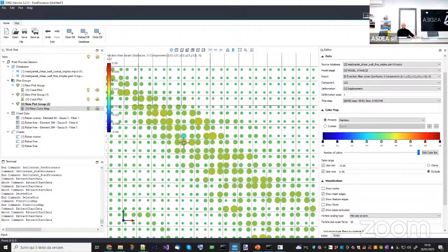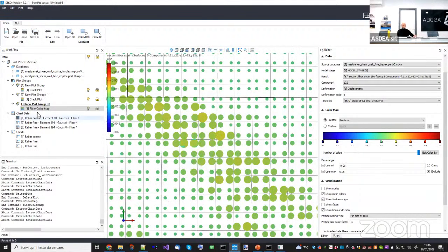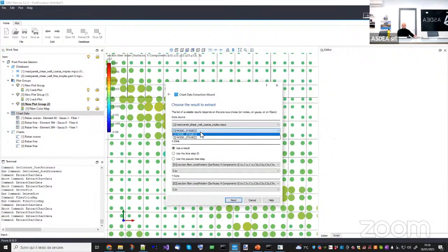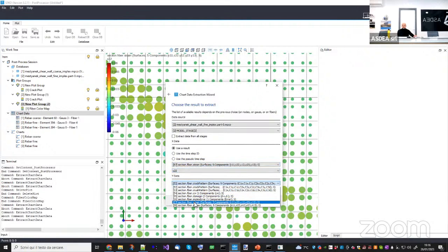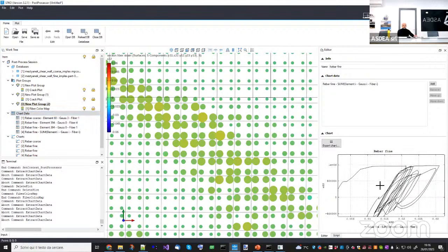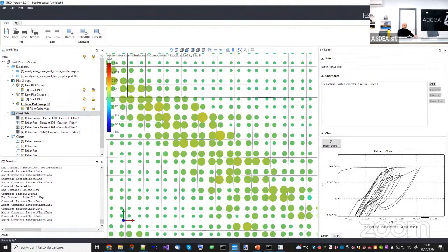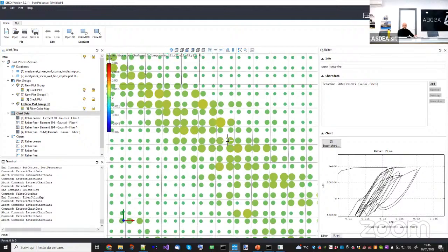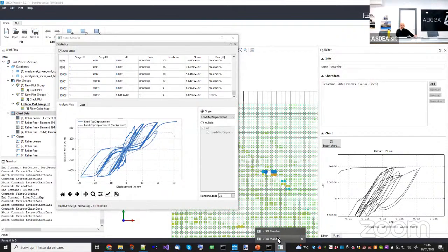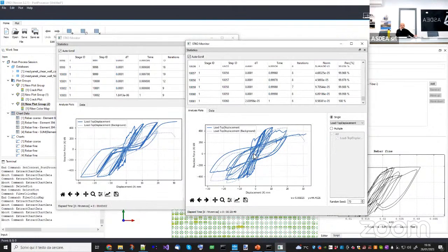So if I extract, for example, this one, probably before I picked one rebar that was not too much into plastic regime, but this one you will see much more deformation. So fiber strain, stress, vertical, rebar fine. Well, I picked two of them now. But as you can see now, the deformation is much larger. It's reaching values of 0.03.